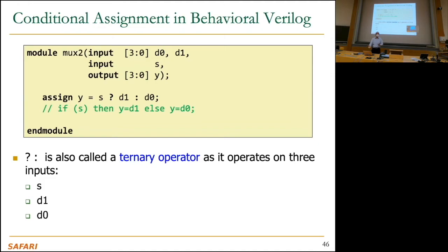And it's beautiful that we can describe it this way. We don't have to describe a multiplexer using gates here. This is behavioral. The gate level implementation, I don't care. Eventually this gets synthesized, and hopefully somebody does a good job with that synthesis so that I get a good gate level implementation. What I care about is the functional description. And this is very functional, as you can see, right? There's no gate specified over here again. There may be many, many implementations of this mux. It could be a lookup table, as we have discussed in the past, right?